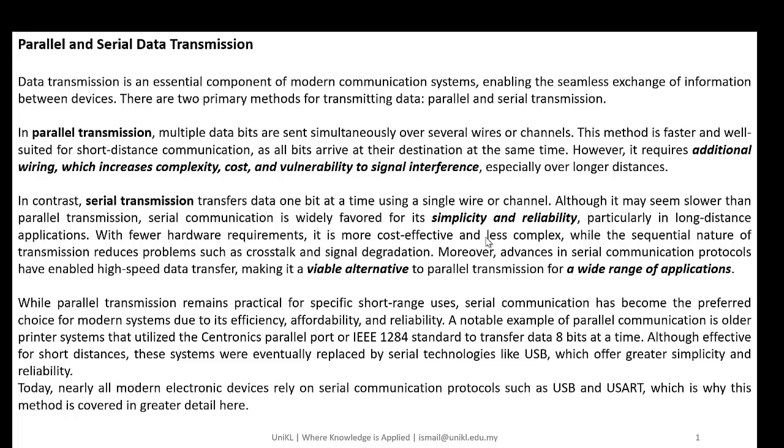There are a lot of applications now using serial communications, either USART: GSM based on USART, Wi-Fi based on USART, GPS based on USART, satellite communication based on USART. Then a number of ICs or devices connected to each other are based on either I2C or SPI, serial peripheral interface, or sometimes one wire communications. All of them are serial transmissions. But there are a few applications that still rely on parallel transmissions, such as the parallel printer, and some others also use it. But it has become rare.